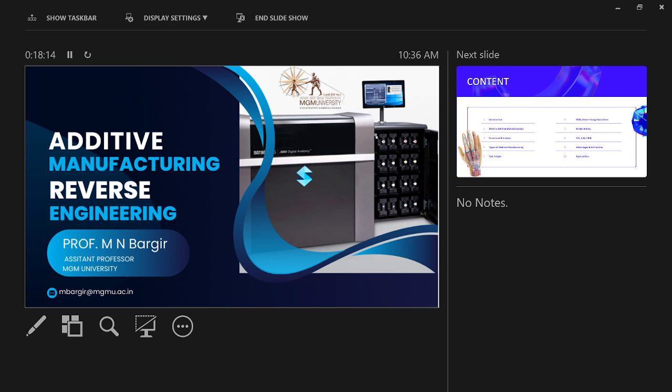But after 2010, the bed size of the machines increased. At first it was available in 125 by 125, or at most 250 mm, the maximum bed size for metal printers. Right now it goes to around 1100 by 600 mm, meaning 1100 on the x axis, 600 on y, and z around 300 to 400 mm.